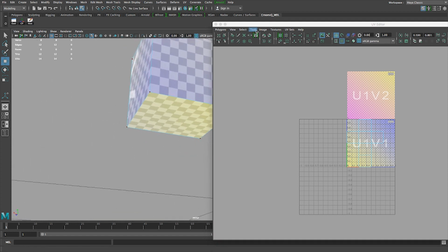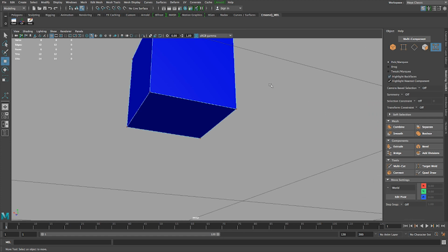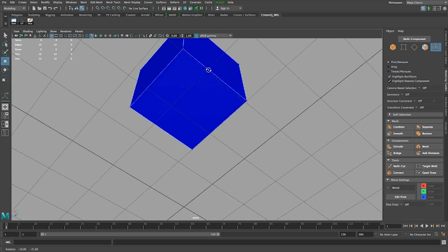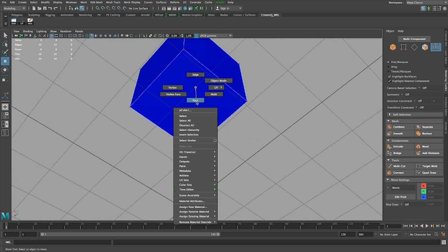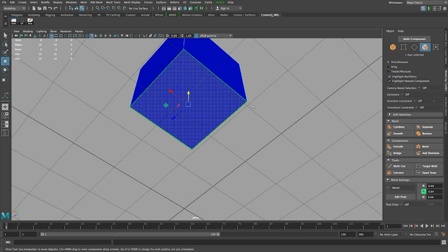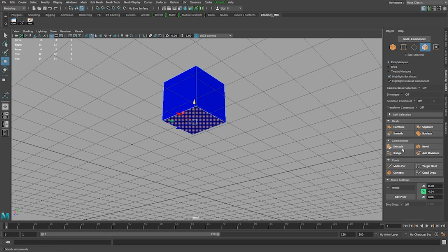Let's select this object. We can close this window for now. And you see when I close it, it's back to blue. I don't see the previews of the cubes. Now let's select this face. So I'm right-clicking to get this bar, select face. I can also just click here for faces, and I'm selecting the bottom face this time. And I'm going to do now extrude.